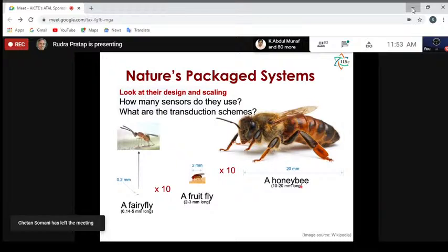So let's look at, all of these are MEMS transducers that I'm showing you. So what are the basic MEMS transducer elements? Very simple structures are the elements of MEMS transducers. It could be a cantilever beam, which is very, very popular in MEMS technology, a membrane structure or a thin plate structure, or a planar ensemble of beams and plates. All of these are simple mechanical structures, right?